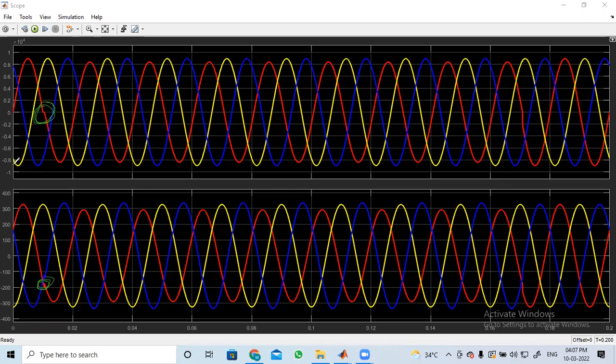The output voltage of the other phases is exactly here, and the R phase is a little bit down here. It is down, is it or not? This way. And here you consider the Y and B phases, and you can see a little bit of change there actually. So exactly a straight line I'm not getting here. It is a little bit of sag, voltage sag out.